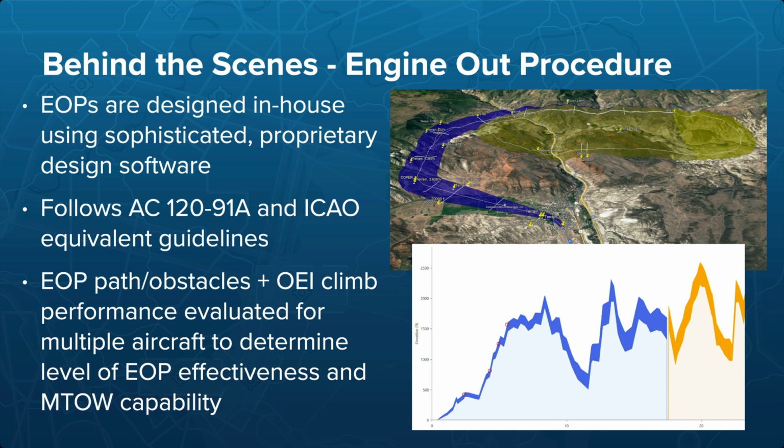So we've all done runway analysis procedures that say, go to the ABC 123 degree radial at 12 DME and then turn right and do a 25 degree bank and keep it within the 175 degree radial. And I think we could pretty much all agree that when it comes to actually flying these procedures in the real world on a single engine, that's going to be a pretty tough procedure to follow. So most of our procedures are RNAV based, and they're checked for reality as well.